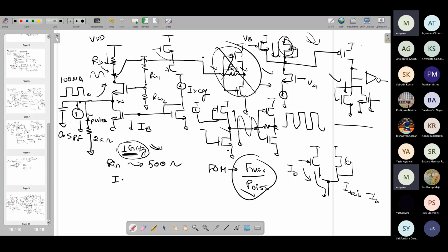Actually this is a little aggressive. On the source side I have given you some aggressive values. Generally the input current amplitude can be up to 1 milliampere also, especially for diodes for communication purposes. And the capacitance value I have also given a little aggressive. This can be 0.2 picofarad, but I am intentionally giving you a little bit more challenging 0.5 and 100 micro. Let us try with that and see what you are getting.